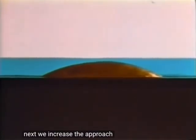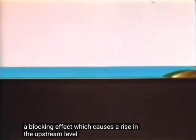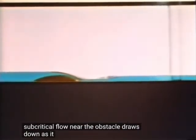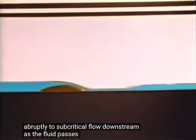Next, we increase the approach Froude number to a higher subcritical value. The obstacle is at rest. As it starts, notice a blocking effect, which causes a rise in the upstream level. When the motion becomes established, the upstream subcritical flow near the obstacle draws down as it passes over the barrier, becoming supercritical in the lee. This supercritical flow in the lee changes abruptly to subcritical flow downstream as the fluid passes through a hydraulic jump.